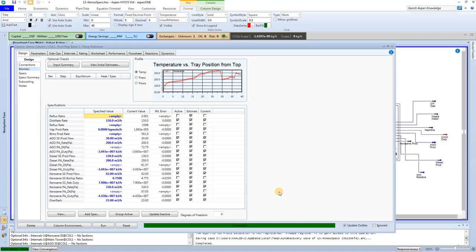One of the most common ways of doing this is to use cut point specification to define the product streams. One of the stream analysis features in Aspen HYSYS, the petroleum assay analysis, can be used to show the distillation cut points under various bases. For example, true boiling point, ASTM D86, etc. So, for example, you could attach petroleum assay analysis to the kerosene product stream and check the current calculated cut points. From there, you could target a wider cut point range using appropriate column specs to maximize production of kerosene.